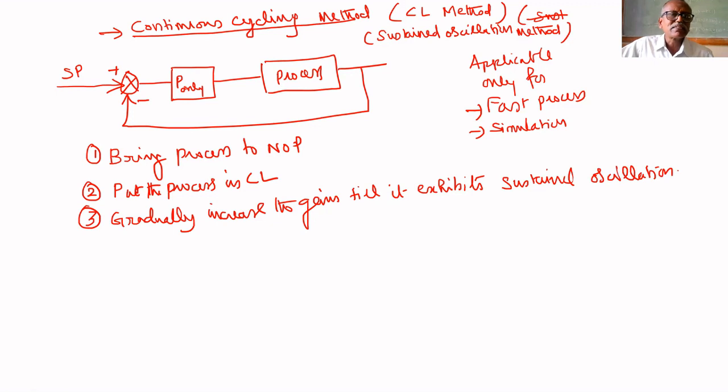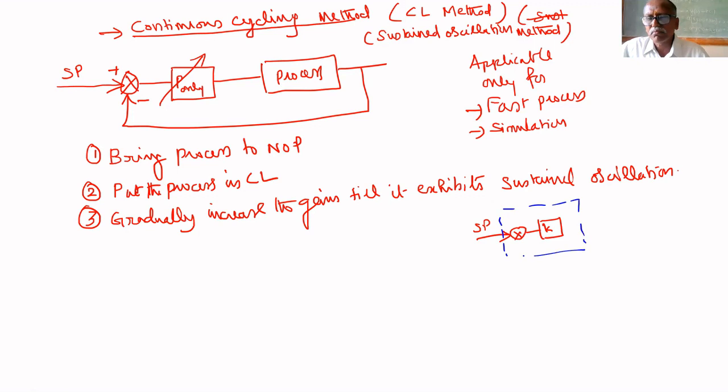We know that if it is a first order process, as gain increases, the pole will move away from the j omega axis. But it is not so in practice. Of course, mathematically the flow process is a zero order process. But what all is in series with it? In our lab, the first one is the controller.